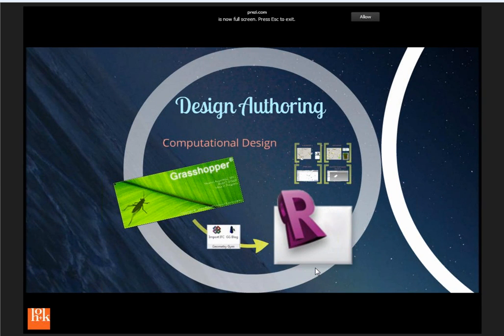Okay. So the takeaway from this is really that you've got complex design data in these Rhino files or in Grasshopper, and really why recreate it? Because generally what happens is they'll dump out an SAT file, you try and make a Revit mass out of it, you'll try and get some floor slabs out of it. Doesn't always work, right? Especially depending on how well that initial mass was modeled. So the key here is use IFC, use this tool, don't redo your work.